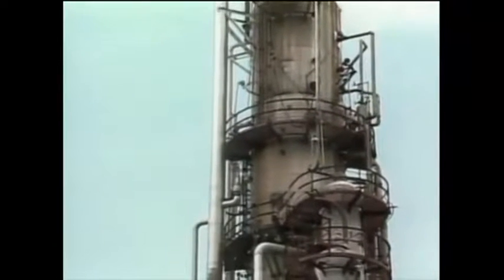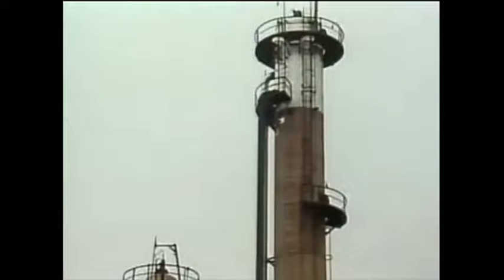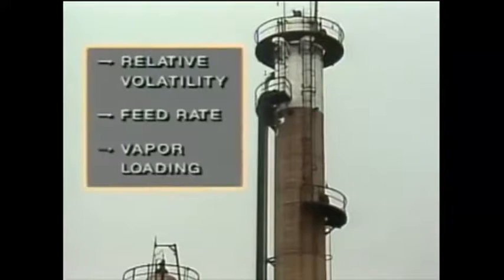Now, keep in mind that a vacuum tower does not operate under a perfect vacuum. Vacuum distillation simply means that the pressure in the tower is lower than atmospheric pressure. One way to separate an azeotropic mixture is to use a solvent. The solvent is a substance that, when combined with the azeotropic mixture, allows the separation of components to take place.